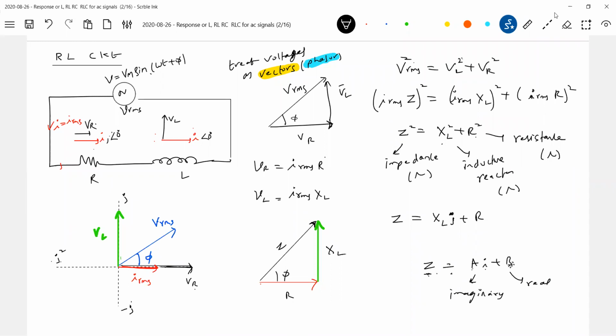What do you mean by imaginary? You said imaginary axis, and there's a real axis. Imaginary means, sir, which will not exist, no? Why? What is XL? XL equals omega L. Go back all. Is omega imaginary or L imaginary? Both are real. Inductor: is it imaginary or a real device? Real device, no? You take a copper wire, make it like a spring, it becomes a solenoid. It will have self inductance. So there is nothing called imaginary and real. Come out of the bookish world of mathematics.